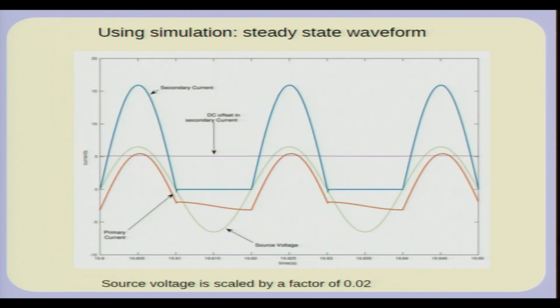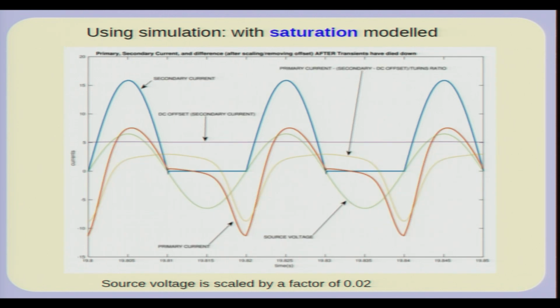So, actually we have replicated this circuit, which is an interesting circuit, by simply numerically integrating it. But what you get as a result is in fact, if you consider saturation, you are able to replicate the results quite well. Why do you get saturated? Because although you normally operate symmetrically in the psi versus I characteristic due to normal AC conditions, because of DC you have actually moved up or possibly moved down.